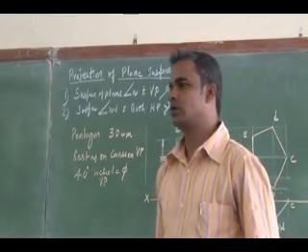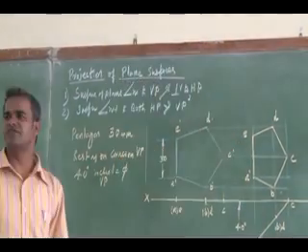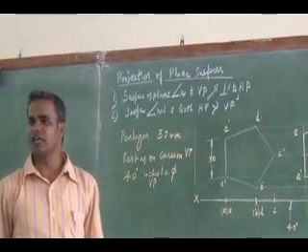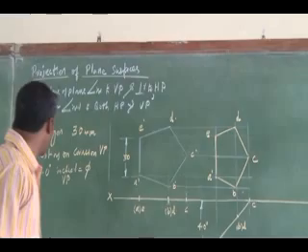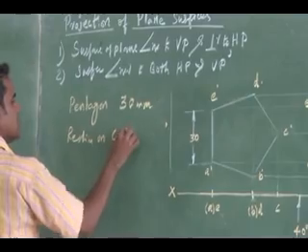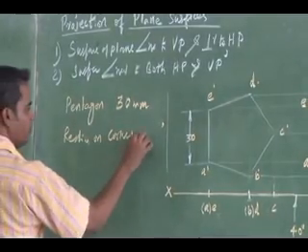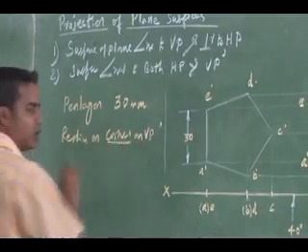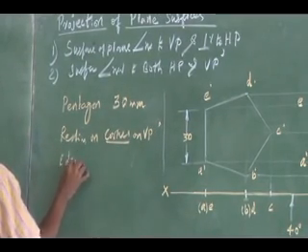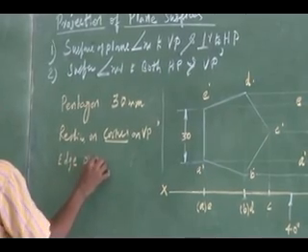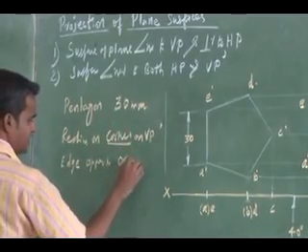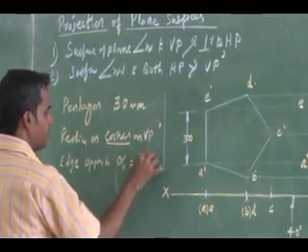Stop. Draw the projections of the plane. The surface of the plane is inclined 40 degrees to VP, and it is resting on a corner on VP. The edge opposite to the corner is inclined at alpha equal to 30 degrees.